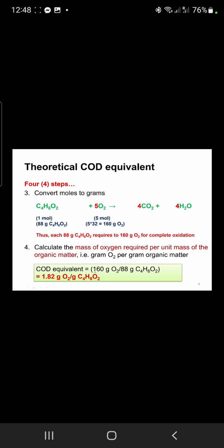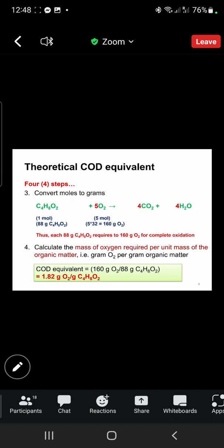So instead of saying 100 grams of acetate, or 100 grams per liter or milligrams per liter of acetate in the water, the 100 grams per liter might be a little too much, but you can say, I have this wastewater or this waste stream that has 182 milligrams per liter of COD, or milligram COD per liter, right? So COD takes all these different concentrations of chemicals or organic compounds present in the environmental matrix into just one single unit, right?